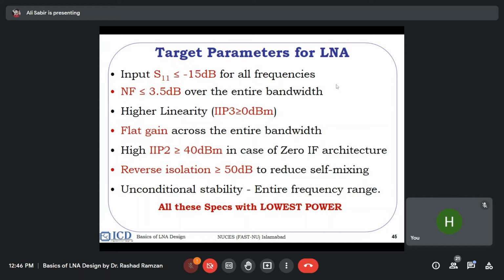What is the currency we have in our hand? There are two types of currencies for on-chip design. First currency is power, and second currency is the area of silicon. So we want the LNA to take small area and also little power.